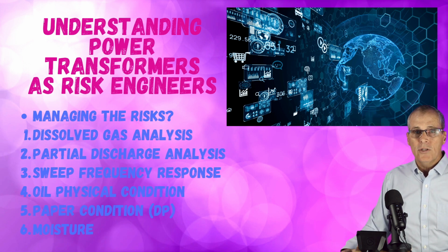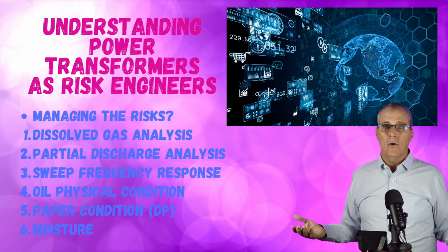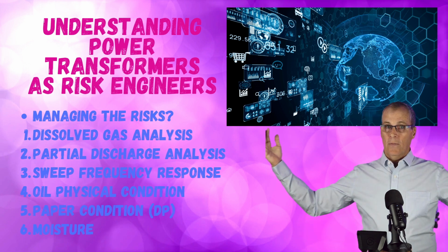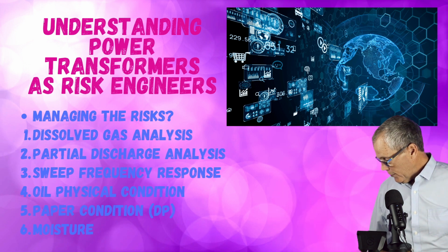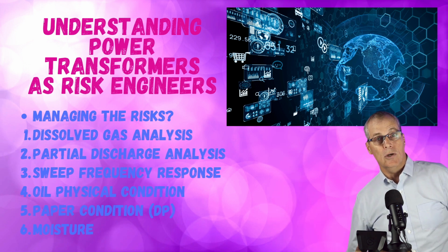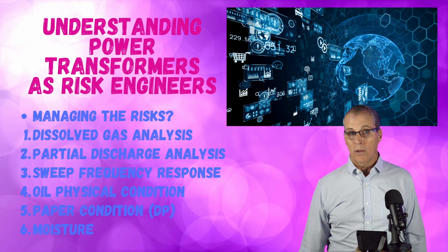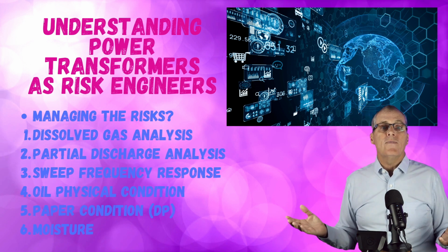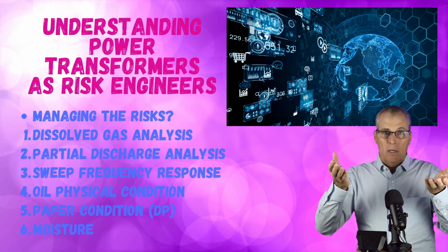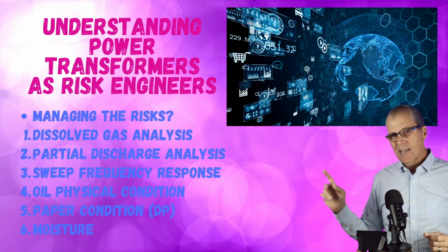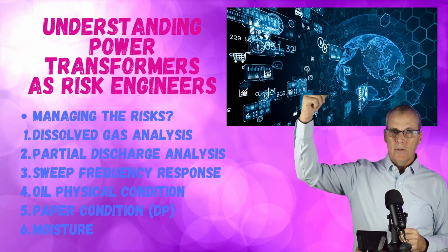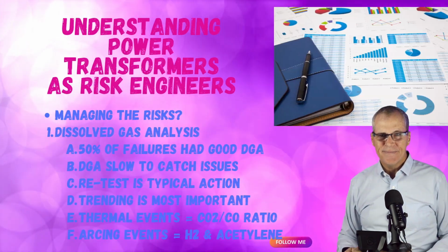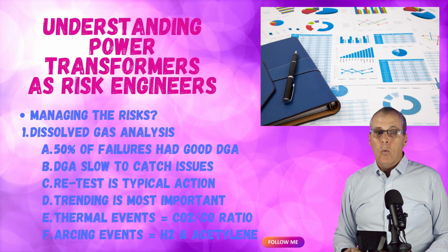We'll talk about moisture. Now, oil floats on water, right? So you can have a big transformer with 30,000 gallons of oil, and there can be a couple of inches of water on the floor or on the bottom of that transformer. It won't really affect anything if it's not up in the core. Now, the lesson we'll talk about later is what happens if the moisture comes in from the top. Stay tuned, you'll see about that one. All right, now what is DGA?